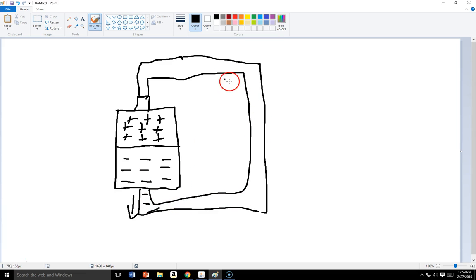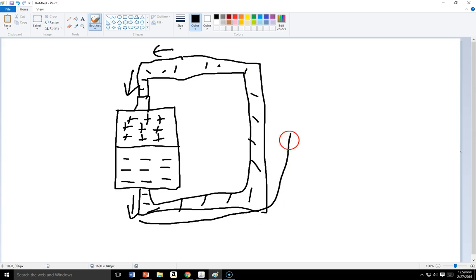Now the wire itself has electrons. So there's electrons here, everywhere, right? Well, at the same time that these are pushing these electrons this way, the positive is attracting the electrons this way. So you have a push, you have a pull, and the electrons are going to start flowing. In fact, all the electrons in the wire are going to start flowing simultaneously. So it's not like there's this push, like a domino effect, where they kind of work their way through. It's more like all at once, everything's going to move. Everything's going to start moving together, all the electrons in our circuit.